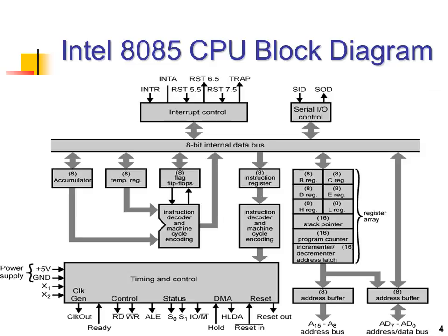Generally, what is meant by program counter? A program counter is used to store the address of the next instruction ready for execution. The 8085 is an accumulator oriented microprocessor which takes one input from the accumulator and another input from the temporary register. The 8085 microprocessor has an 8-bit flag register which has 5 active flags, and the timing and control unit will provide basic timing to the architecture.